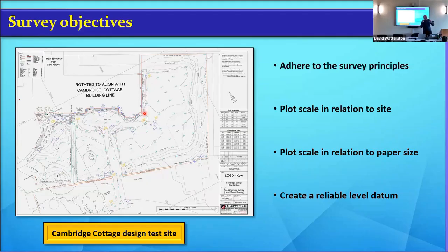That's probably where the surveyors used a laser-based distance to get in there. One bit he's hit the brick. The next time he's observed it as a check, he's hit the grouting between it, and the grouting can either be outside or inside. And the next one was another brick low. So the bricky was probably out by a couple of mil, but it was the difference between the grouting to the face of the brick.